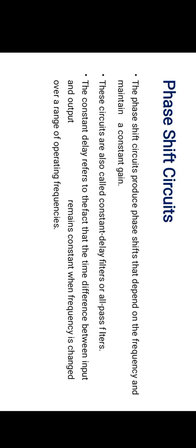The phase shift circuits produce phase shifts that depend on the frequency and maintain a constant gain. These circuits are also called constant delay filters or all pass filters. The constant delay refers to the fact that the time difference between input and output remains constant when frequencies change over a range of operating frequencies.